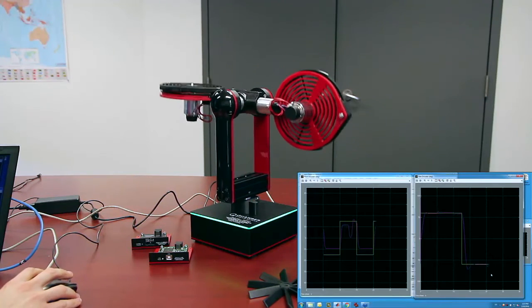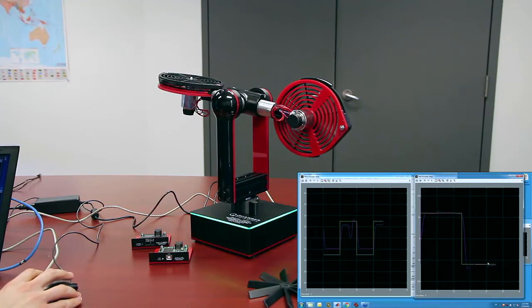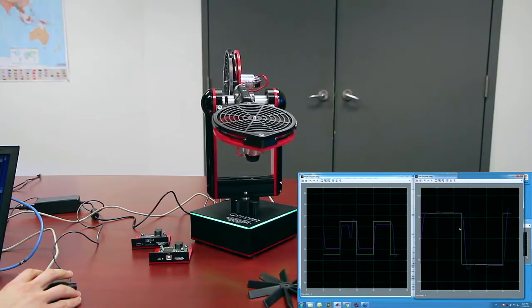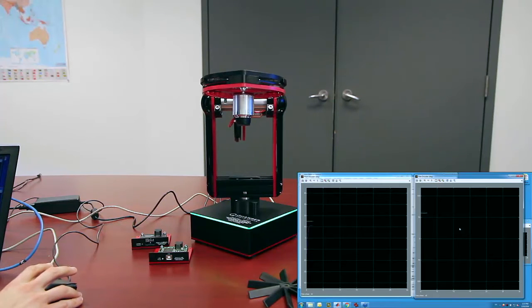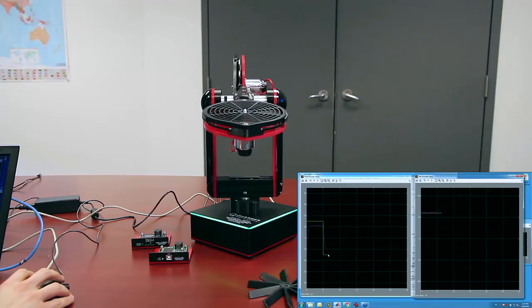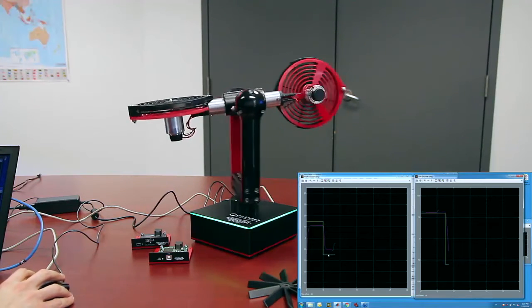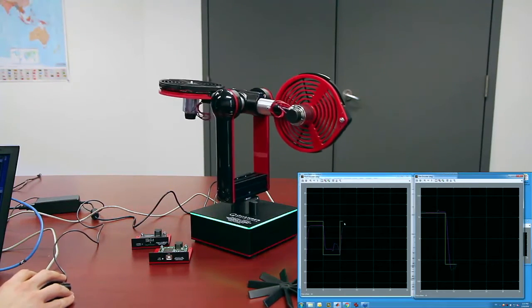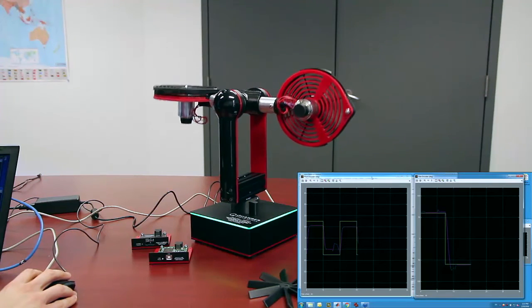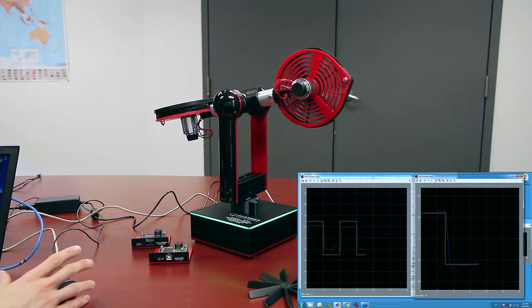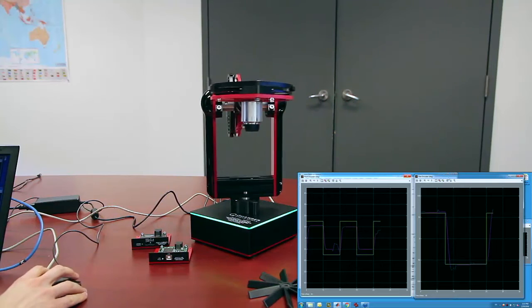Now you'll see that when it's changing in the yaw or the pitch, there's a lot less perturbation, right? Because this is a coupled controller design, you get a much better performance, right? The tracking of the pitch could be improved, of course, but this is just a sample and example gain. But as it's moving in the yaw, you get way less perturbation along the pitch. So I think that gives you a second approach of what you can do. Again, the LED right now has changed color.